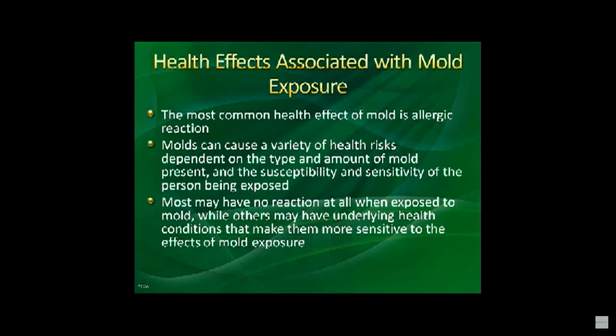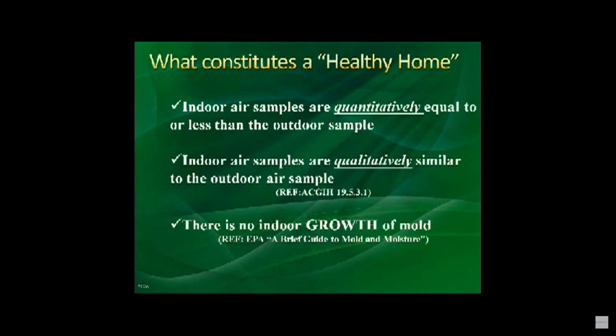What the industry defines as a healthy home scenario for mold is if the indoor samples are quantitatively equal to or less than an outdoor sample or a control sample, and if they're qualitatively similar. This comes out of the American Conference of Governmental Industrial Hygienists. A brief guide to mold and moisture from the EPA states no indoor growth of mold is acceptable.